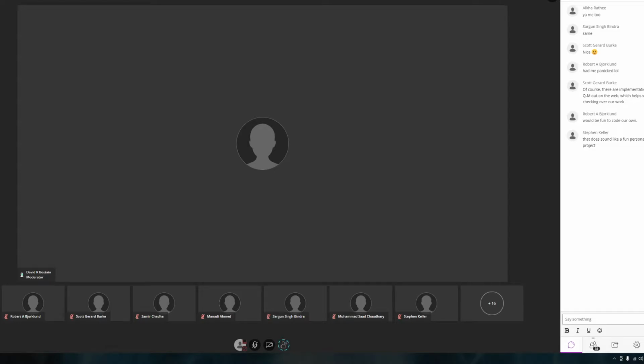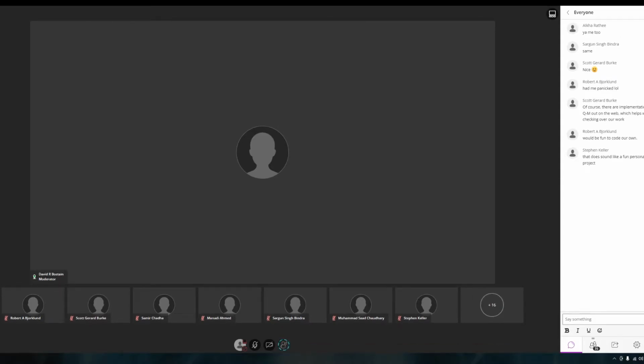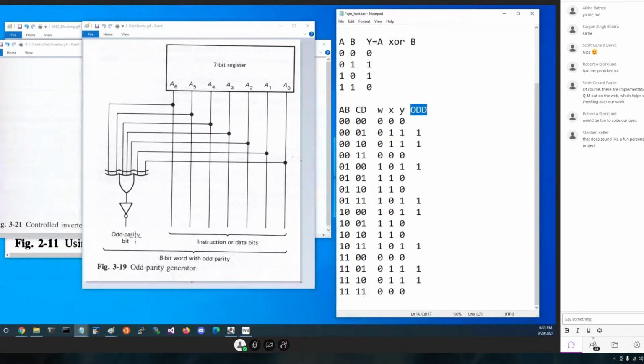Now, this is good because if I ask you to build something which could transmit an ASCII character, one of the steps would be to generate parity. It's easy to generate mark and space parity because you either just add a 1 or add a 0 to the end of it. Even and odd, that's easy to do now. All we need is to have XOR gates and an inverter. If we wanted to have no parity, well, it doesn't really matter what we hook it to. So we have another tool in our tool set.